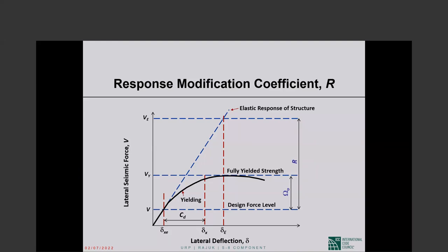We know that if the design earthquake were to actually hit, the displacement of level X would be much higher than delta sub XE because the V does not represent the force that will actually be induced in the structure by the earthquake. Okay, that's what we are designing for. But the earthquake probably will induce more forces and definitely more displacements.